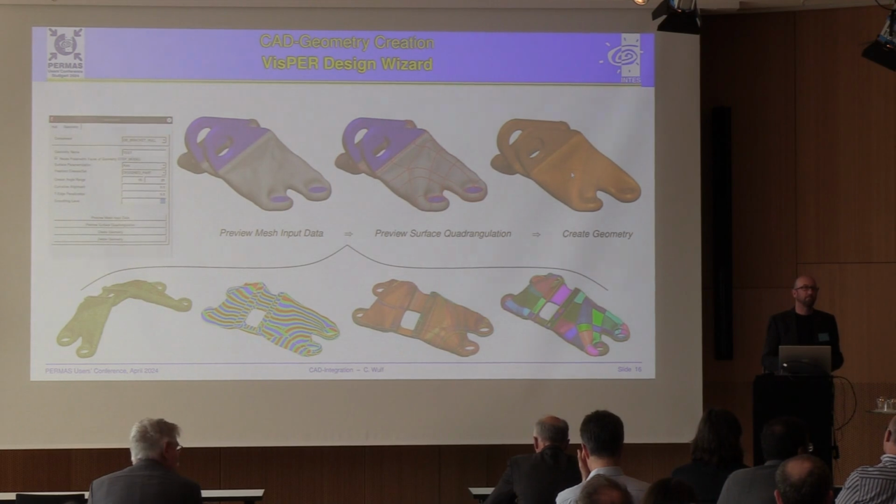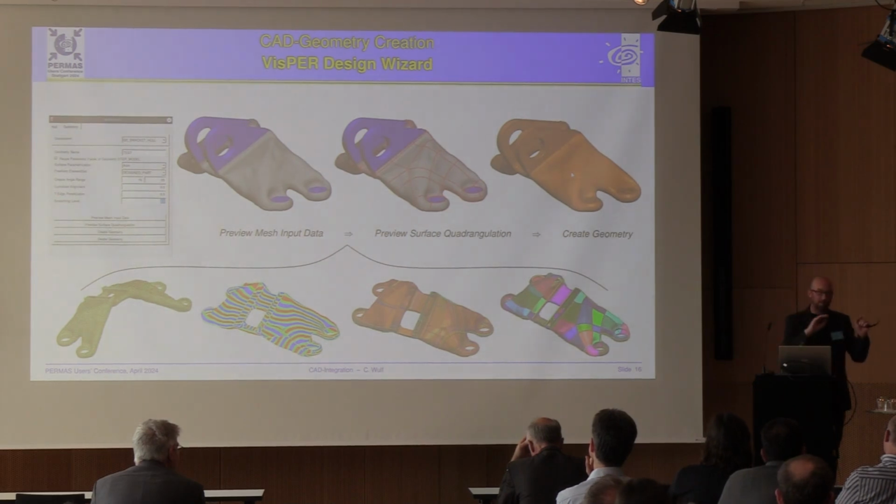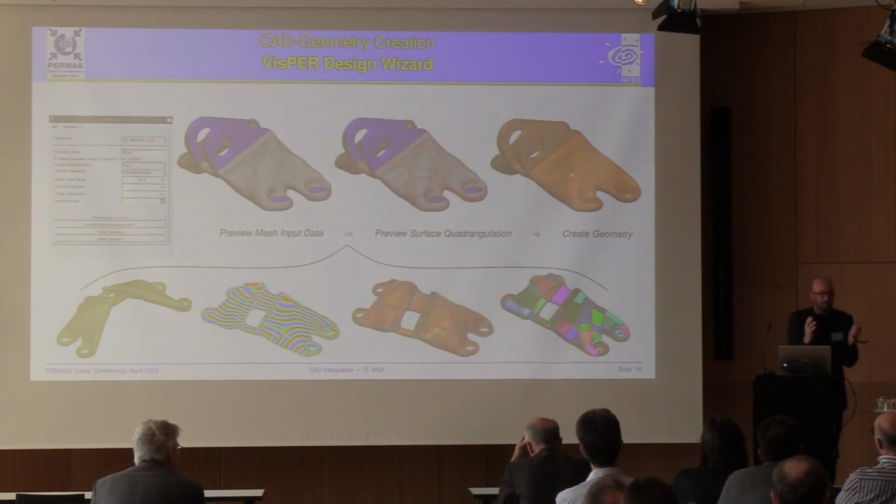And another question is about the smoothness of the patches that fit together. Is there a criterion for this, or do you leave them at the edge that you created, so the normals are looking in different directions? No, we just have a simple parameter, more or less. Up to now we don't have concrete values for normals or deviations. We just give the user something similar to a slider, a value from strong smoothing to small smoothing.